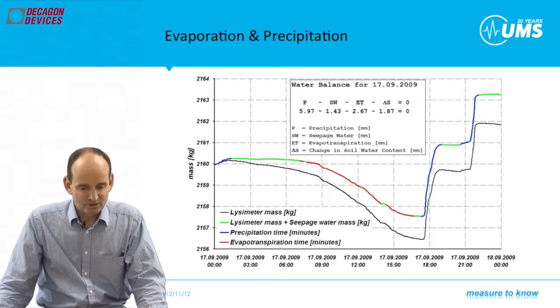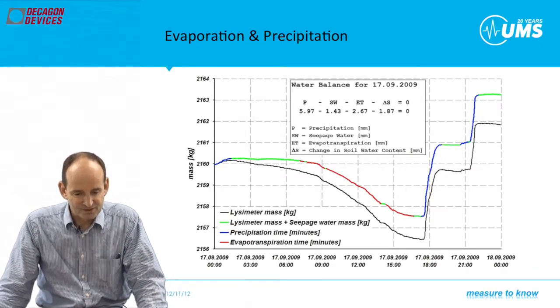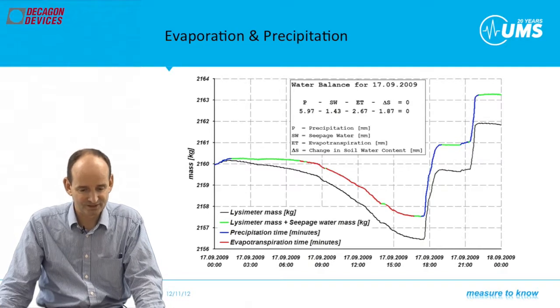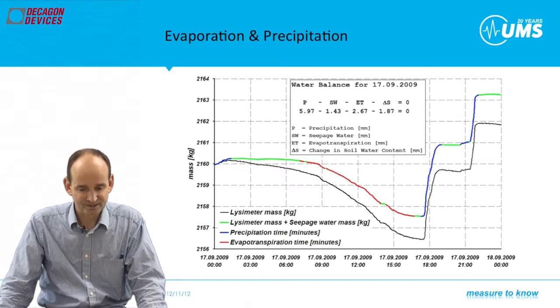If we then have a look only at the drainage weight, we know in the depths of the bottom plate the amount of water that passes through the soil. This is the groundwater recharge amount if the bottom plate is deep enough. However, the higher the time resolution, the less it is a simple addition of losses and increases, because the signal noise would overestimate the results.